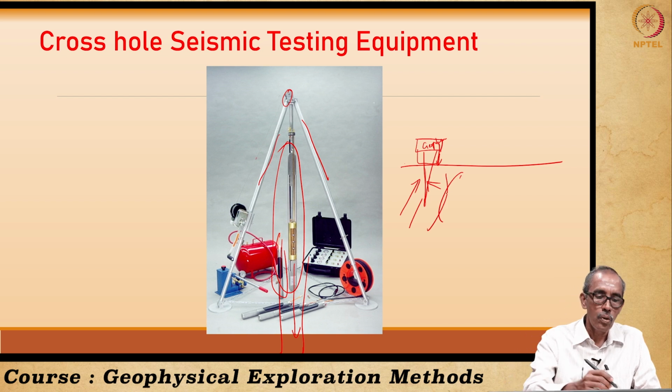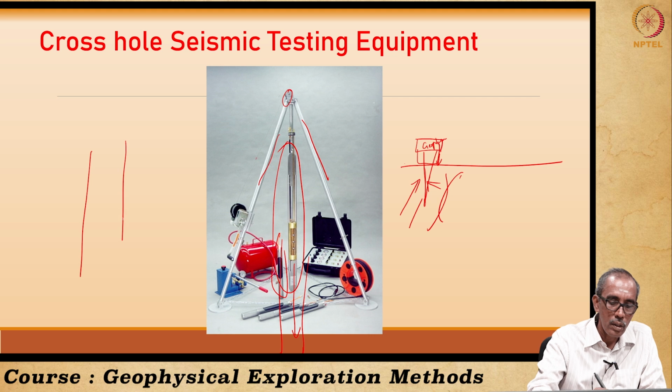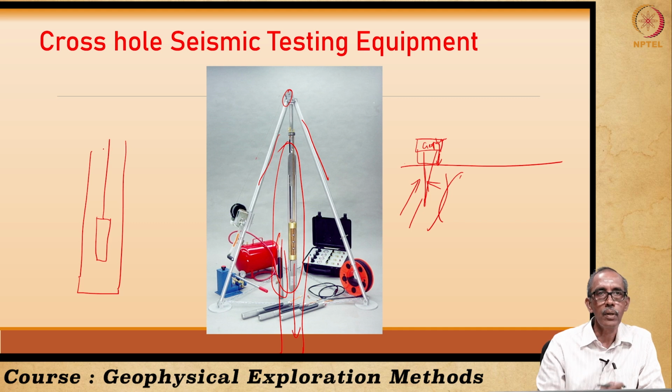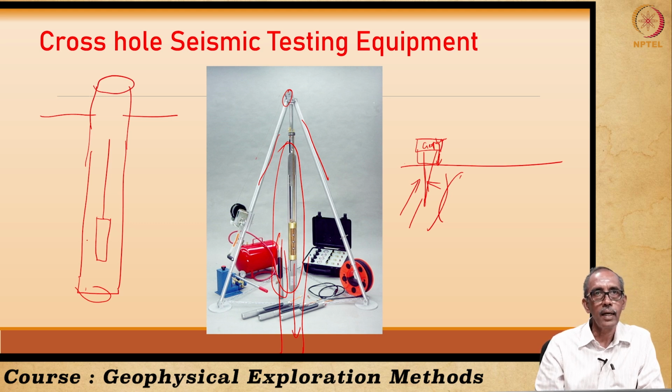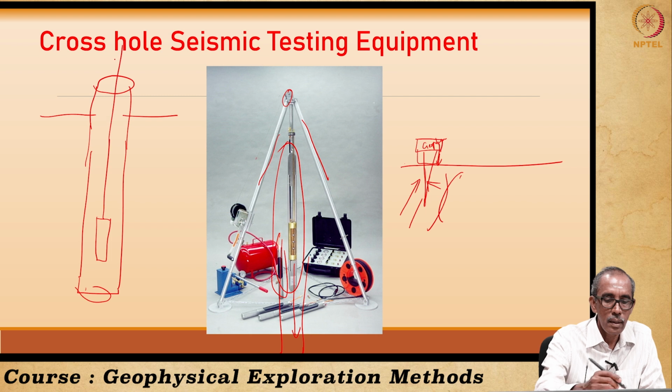In the case of a borehole, we are going to keep the geophone something like this. It is attached to a cable. So, the geophone needs to firmly touch the wall of the well. This is a borewell, a borehole, the ground surface, this is the well, and the geophone needs to firmly touch the wall. It cannot freely hang at the center as you see in the picture now.